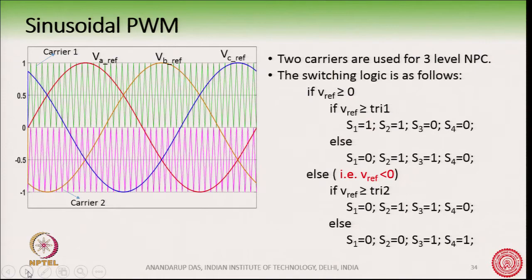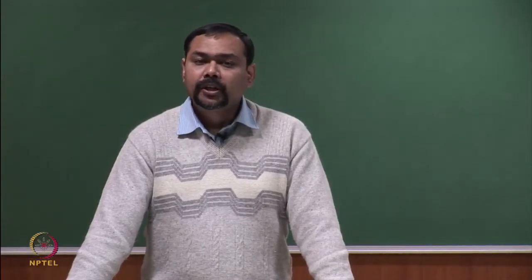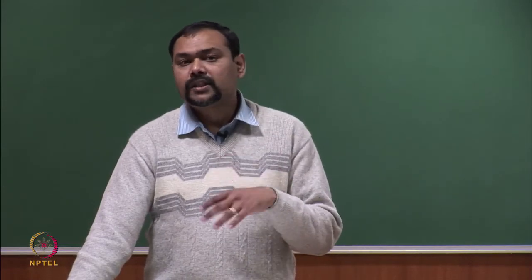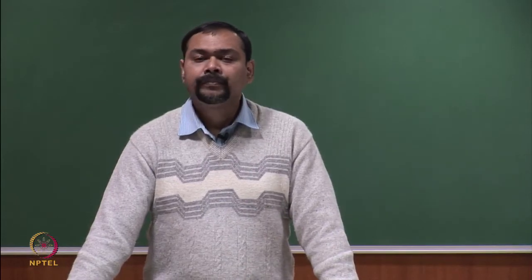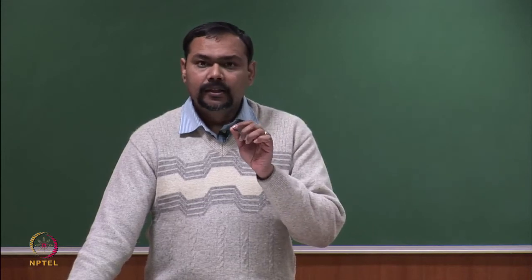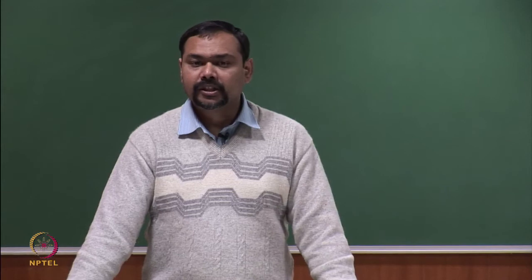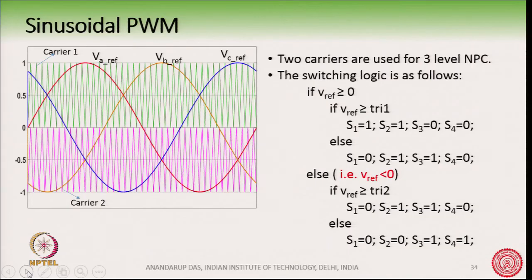However, level shift PWM gives slightly better harmonic performance as compared to phase shift PWM, because sometimes in phase shift PWM the 0 magnitude vector is switched for certain modulation index, and that is why we will focus on the level shift PWM here.